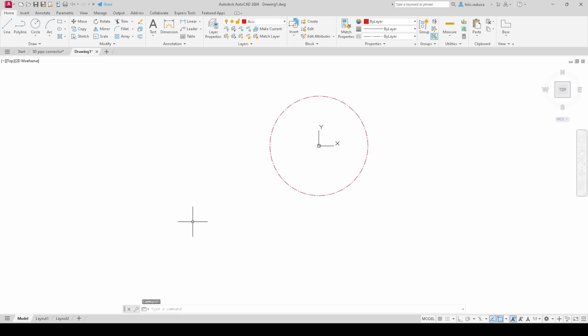So to build that, we'll go back, and we need to draw the axis line so that it extends outside of the second radius of 10. So we need to draw that axis line to be 40 plus 10 and plus another 3, so it should be 53. So it's a line, starts from the center and goes to the left, so at minus 53 comma 0, and tap enter twice to have that.